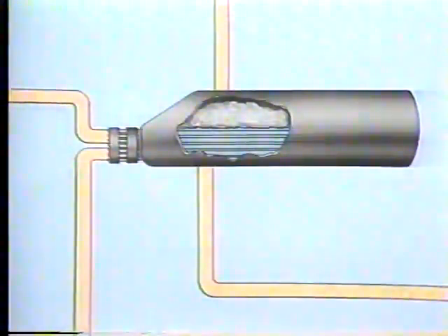In your training, you've probably learned about single-element control systems. So a good way to introduce multi-element systems is to see how two single-element systems working together keep a single controlled variable at set point. Let's take a look at an example of how this is done. Here we see a simplified illustration of a heat exchange process that's used to convert water into steam for use in the plant. This particular system is designed to keep the steam leaving the heat exchanger at a specific pressure.